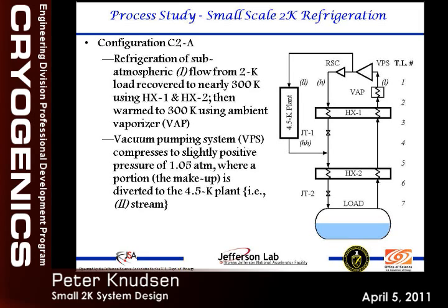So this heat exchanger sees an imbalance. This is the flow ratio we were talking about, high stream to low stream. That's an important parameter that we'll look at. This supply pressure is an important parameter that we'll vary and look at. And the total NTUs of these heat exchangers, basically how long these heat exchangers are, we'll look at as well. And then this is the 4K system, so it gets 1 atmosphere helium in and then spits out 3 atmosphere, 4.5K, essentially saturated liquid out here.